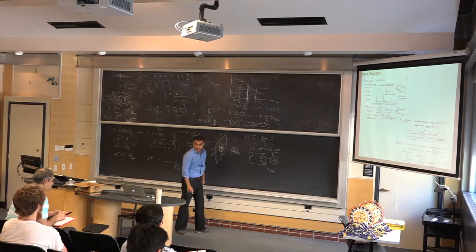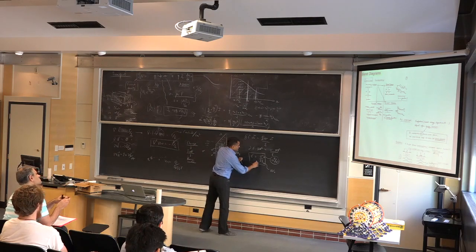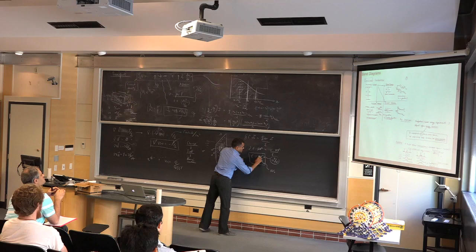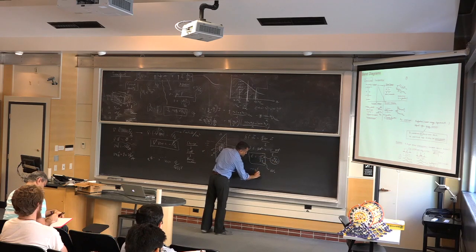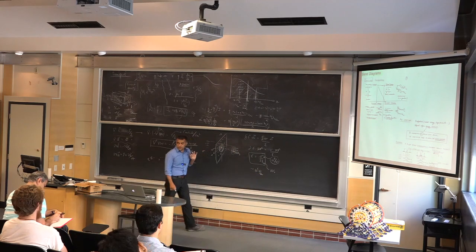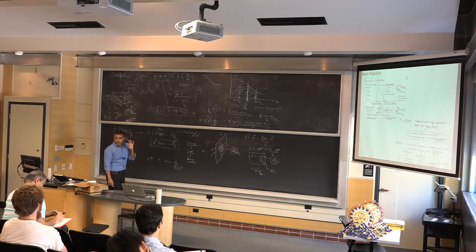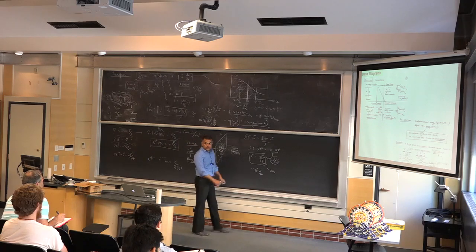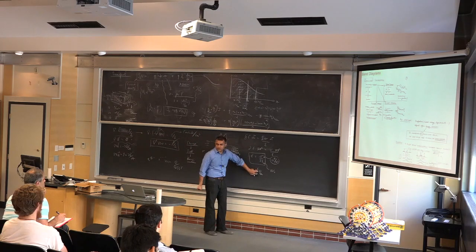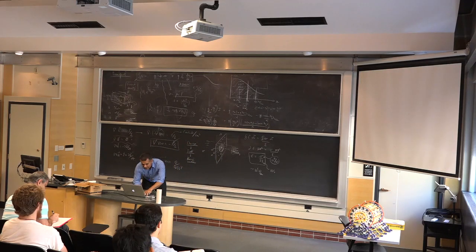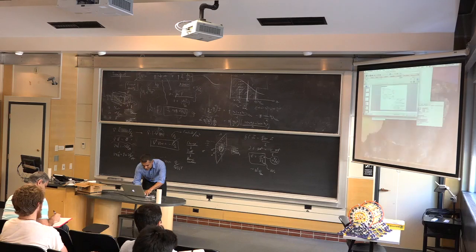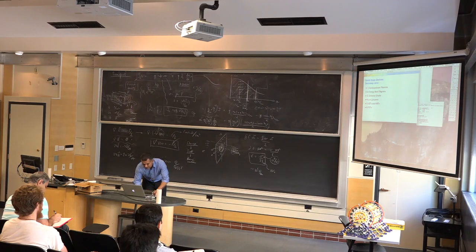You can plug in the numbers, and there's a Q here, the electron charge, but this is the sheet density. So you will get roughly 10 to the power 6 volts per centimeter. That's the field you will get. So 1 megavolt per centimeter, if you have 10 to the power 13 per centimeter square sheet charge density, a very useful order of magnitude. So if you have 10 to the power 12, I have 10 to the power 5 volts per centimeter, order of magnitude of fields. And again, this is obviously nothing very fancy. You can make a nice little plot of it.